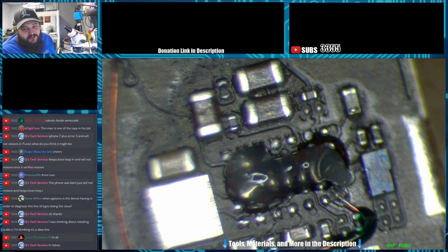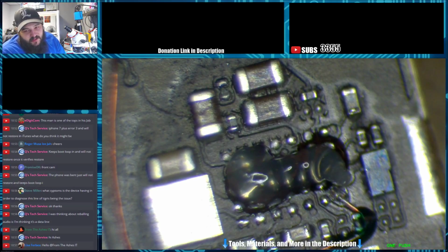In this situation, I've replaced Tigris 3 times and we still have no battery information, and I assume that since we still have no battery information, this most likely is an issue with the line that goes from AP to Tigris.